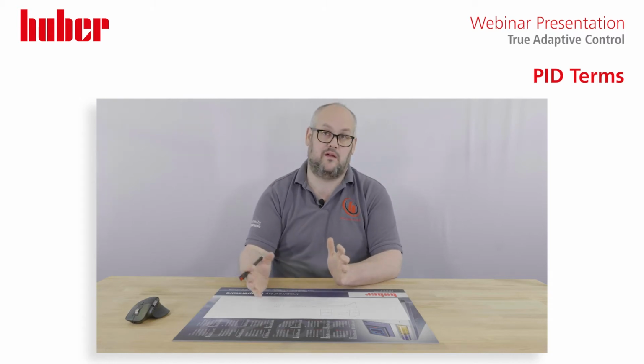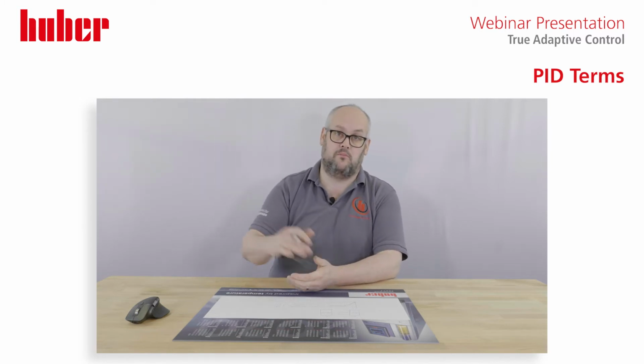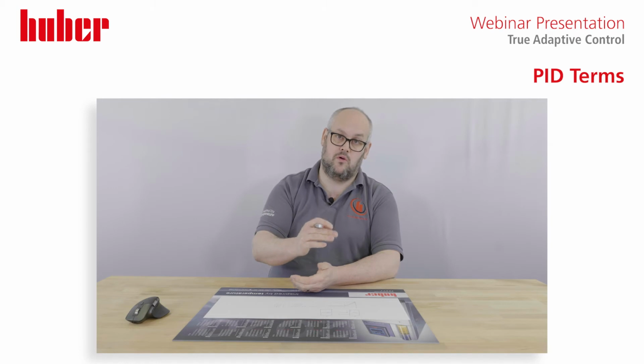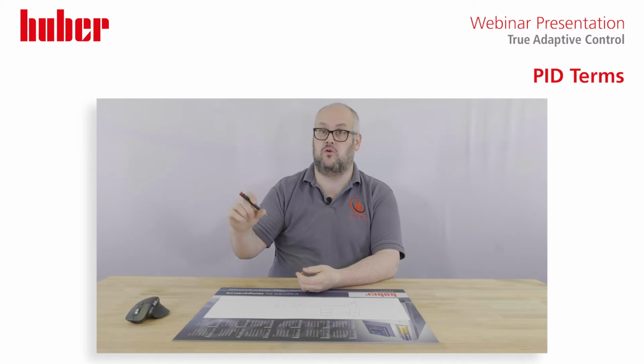On a Huber unit with a Pilot 1, you can go into the menu and select: do I want option A or option B? Under-damped or critically damped. We don't call them that because it sounds a bit too technical. We've tried to go with layman's terms. So if we go into our Pilot 1 and go to menu, temperature control, TAC, configuration auto, under the heading control dynamics, you will find two options.